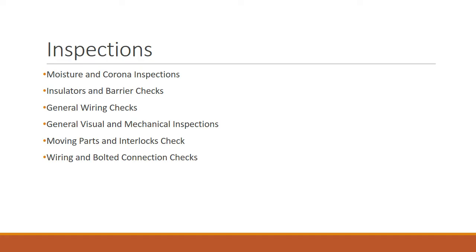Physical damage or polluted surfaces on electrical insulators should be looked for. Corona erosion, marks, and tracking pathways are usually visible on the surface of insulating parts as a result of electrical distress. You should check for appropriate installation and operation of the barrier and shutter assemblies on the switchgears. All active components should be tested, and mechanical indicating devices should be checked to ensure proper operation. You should also make sure there are no obstructions in the vents and that filters are in place. To keep rats and small animals out, screens should be installed above ventilation apertures.